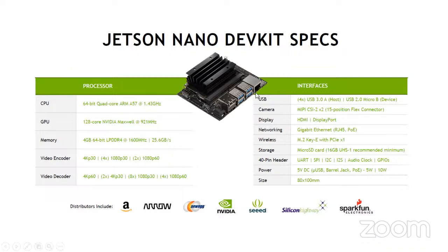But in case you don't have these essentials, then you have another option to communicate with the Jetson Nano. You can use this USB port here. This USB port is the output from the Jetson Nano. The Jetson Nano has a serial UART, so this USB port will give access to a COM port, a communication port, of the Jetson Nano.